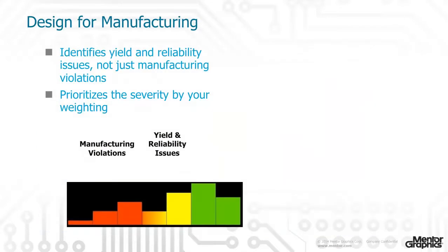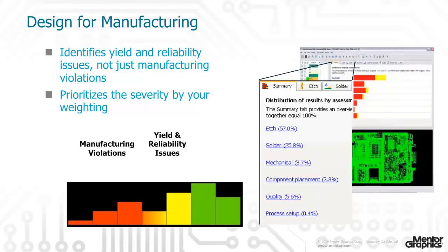After applying the manufacturing process rules to the model of your PCB, the manufacturing process risks are presented back to you according to their severity and the manufacturing process that has a compatibility problem with the product as currently designed. Notice that the DFM analysis rules are not presented as go-no-go, like design rules checking.